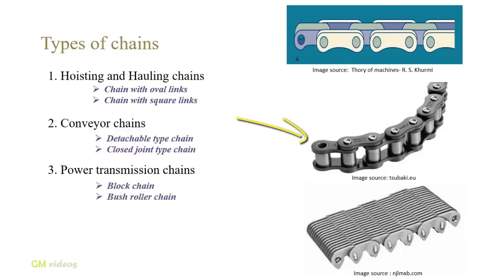The second figure depicts a bush roller chain. It consists of outer plates or pin link plates, inner plates or roller link plates, pins, bushes and rollers. A pin passes through the bush, and is secured in the holes of the roller, between the two sides of the chain. The rollers are free to rotate on the bush. It protects the sprocket wheel teeth against wear. A bush roller chain is extremely strong and simple in construction, and provides good service. There is little noise with this chain, and it may be used even when the lubrication is little.